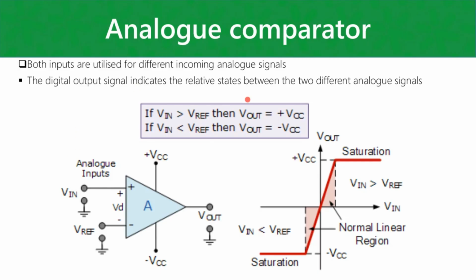All right, so the analog comparator. You guys will see in the textbook there is quite an interesting drawing or graph on how they explain the operation of this. So typically you will have a reference signal on one terminal. Now you can swap the reference and your input, so you can have it either way, it doesn't matter.